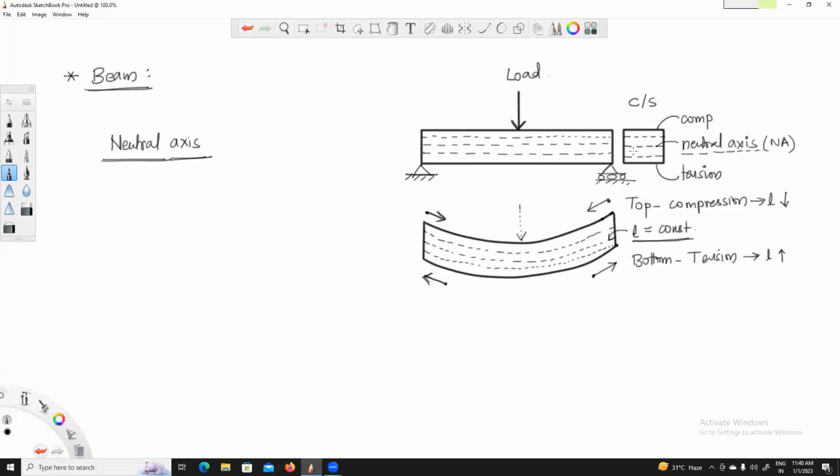And again, if you go through the cross section of the beam, this is in fact a three-dimensional body. So you can consider this beam as a three-dimensional object. Let me draw this three-dimensional object. So this is our beam. This top surface, this top layer, is under compression because we have loaded this beam with a point load in the vertically downward direction. This bottom layer is under tension, and let me draw this diagram completely.